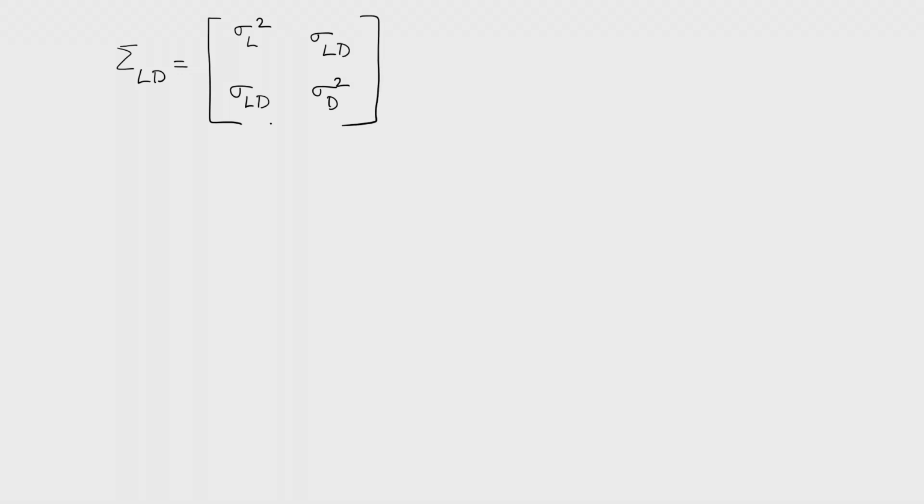The next is, what is the maximum error here? Again, take the example of the latitude departure measurement. Here we have sigma L square, sigma D square, and sigma LD. Now if I take a couple of samples of length and bearing, then I try to find out latitude and departure for each line, and let us assume that each line is representing a sample.